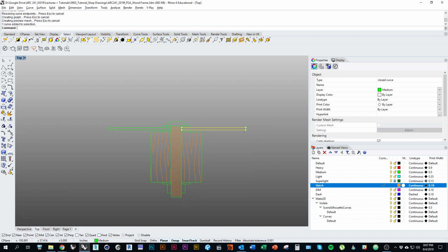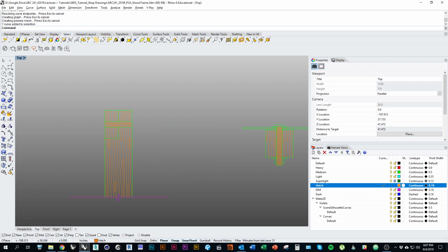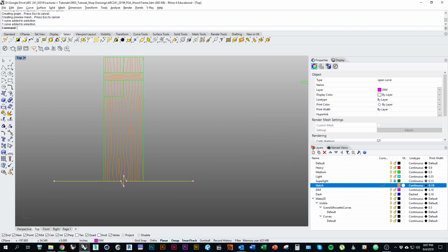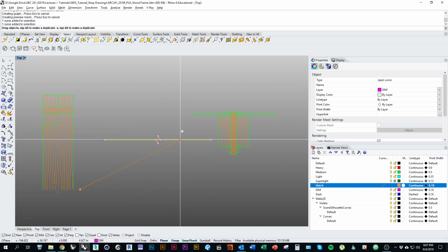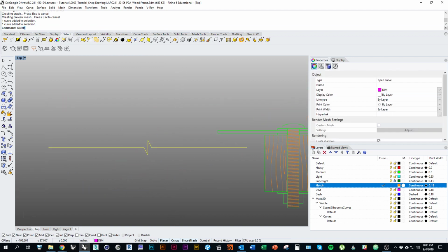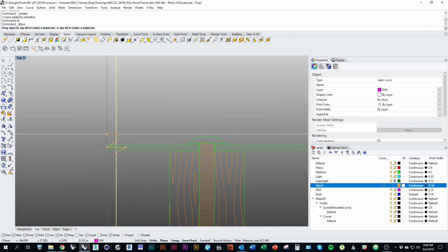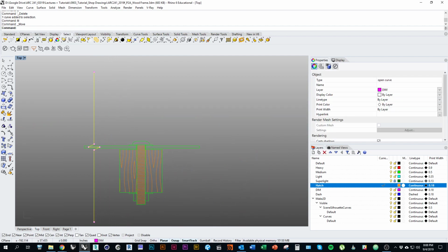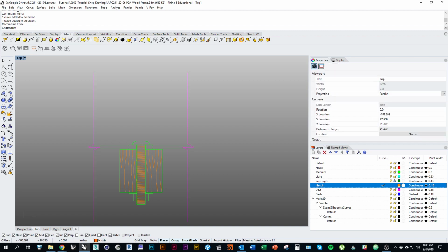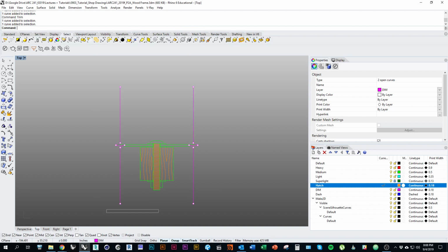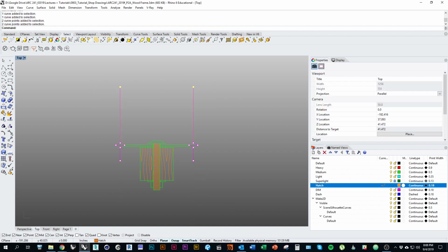And then finally I want to hatch my seat. So I'm going to copy my little cutoff that I drew over here. I'll just drag it and tap Alt on the keyboard. Get that in place. And then I could just mirror it. And I'll use those two lines to trim the excess once again. And they're a little bit big, so I might just move these endpoints up. Otherwise, we're going to need a lot more space on the page than necessary.